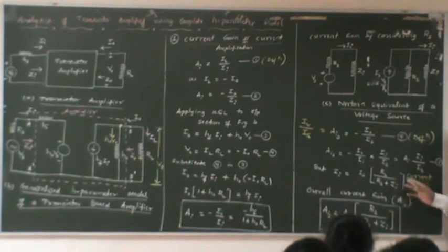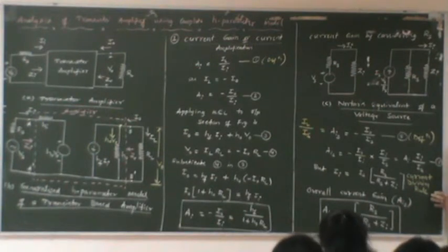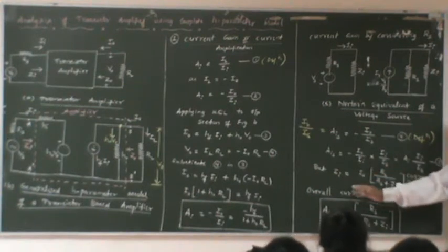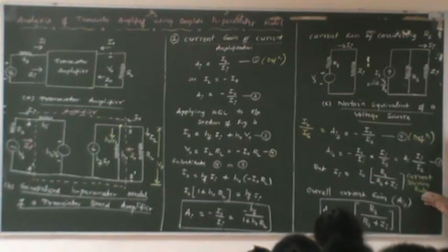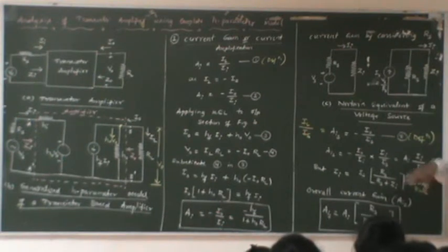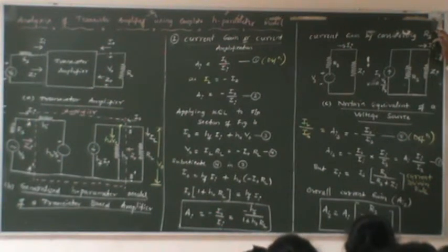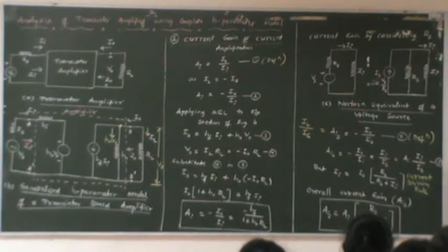Explaining this is not convenient because this is actually the basics of electrical networks. Now I can explain how I got this expression. For the time being, don't worry about this current division rule. The simple technique is, if you want to obtain this particular current, multiply the source current with the resistance and divide by the sum of the resistances. That's a simple mechanism you learn. Otherwise, you can derive this expression, not a problem at all.